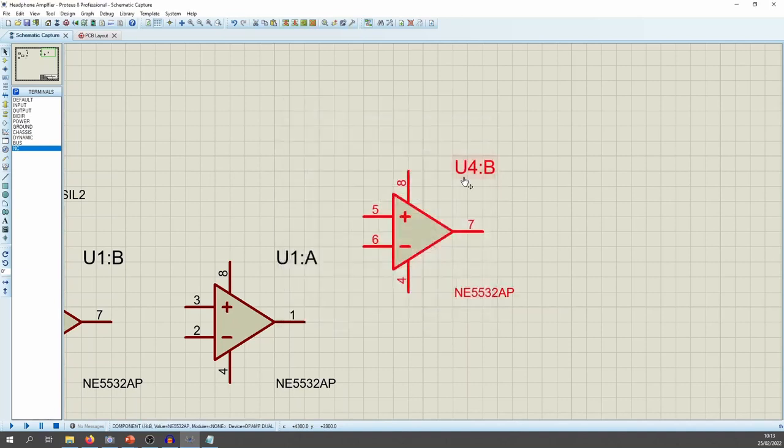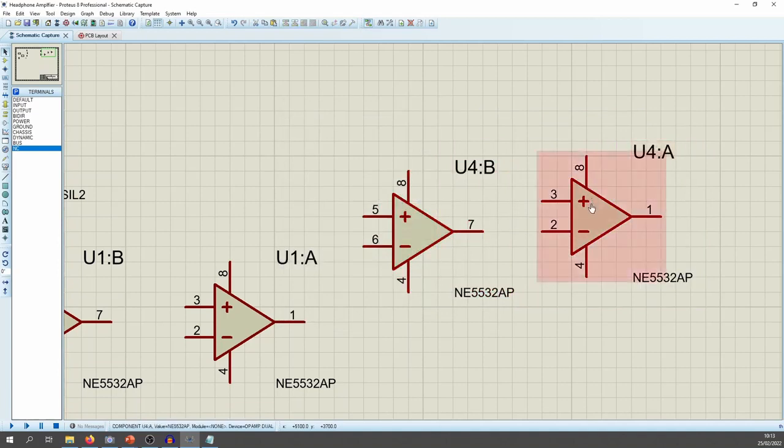So if you put the second gate on, would you then draw the connections to the supply rails as well? You wouldn't have to, because this is actually connected to that. Yes. So if you put power... Draw them in your schematic, but it would know automatically in your PCB layout, wouldn't it? It wouldn't run two routes. Yes. It would allow you to do one.